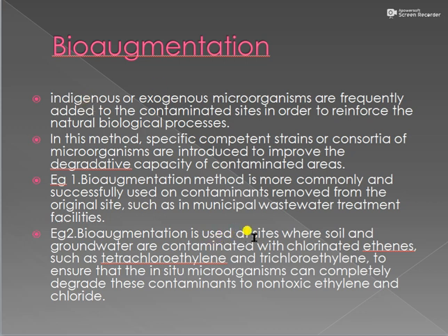Bioaugmentation is more commonly and successfully used on contaminants removed from the original site, such as in municipal wastewater treatment facilities. And it is used at sites where soil and groundwater are contaminated with chlorinated ethenes such as tetrachloroethylene and trichloroethylene.